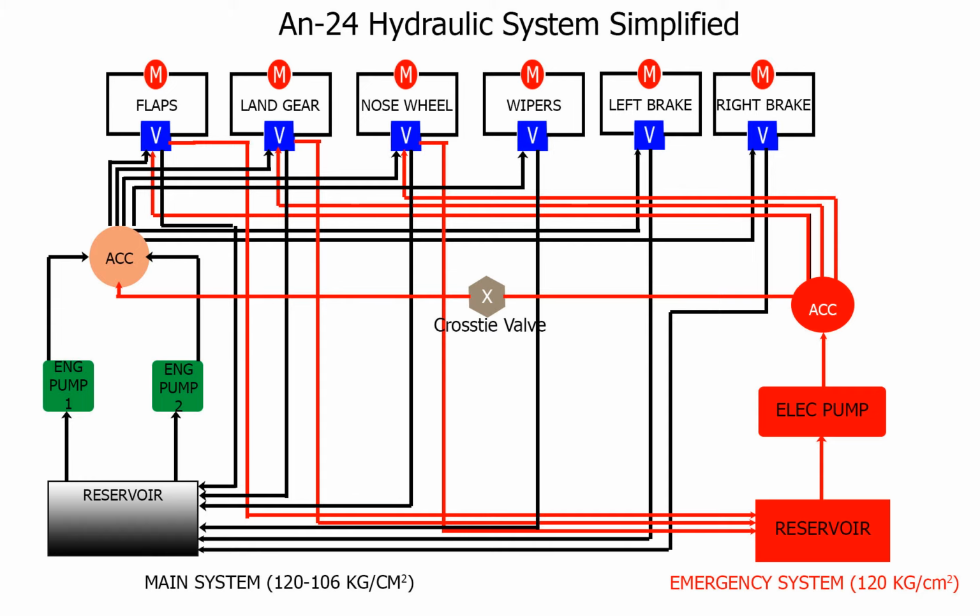The manual states specific devices controlled by the main bus, but then it also says that the main bus controls all the hydraulic devices. So I tried to make the diagram generic in the sense that I included the brakes, but I didn't include things like the ailerons and elevators, so as to stay consistent with the written manual.